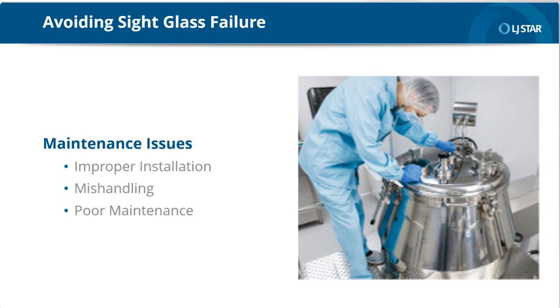As far as mishandling is concerned, using the sight port as a handy place to rest a wrench is never a good idea. Impact from an object creates pitting that makes a stress concentration point, which can cause failure. This is comparable to making a tiny cut or tear on a piece of paper and then pulling on it. In fact, the same thing is done when glass is cut. A glass cutter scores the glass, creating a small depression in the surface, and then a bending moment breaks the glass along the scratch surface. This is like a sight glass with a surface scratch and pressure behind it, creating a bending moment.